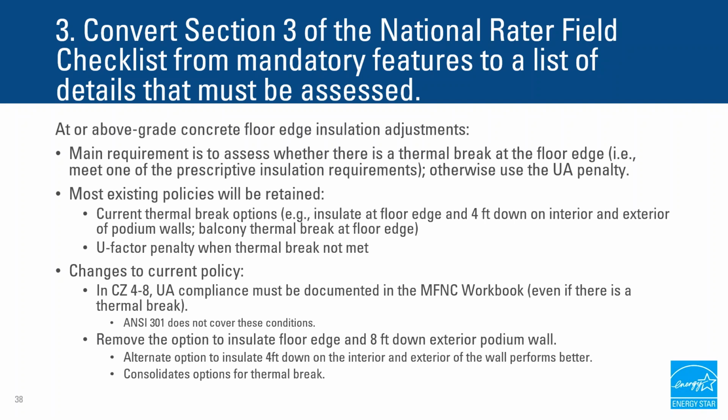And then we are consolidating the overall options for that thermal break. We are removing the option to insulate the floor edge down 8 feet on the exterior podium wall, given that the alternative to insulate 4 feet down on the interior and exterior of the wall performs better.